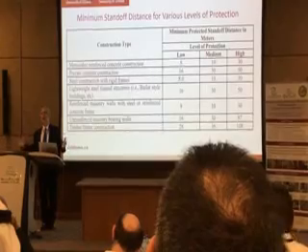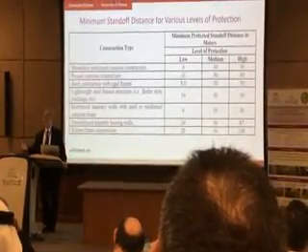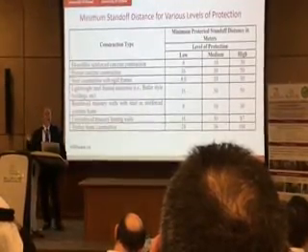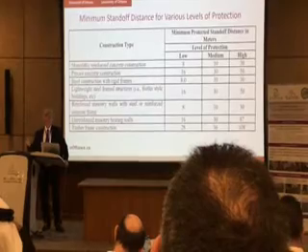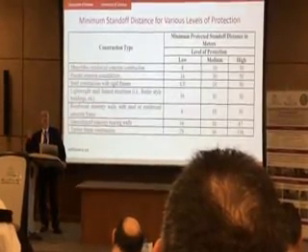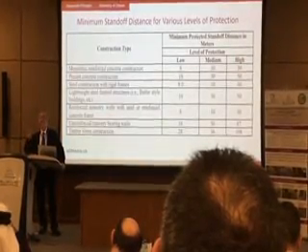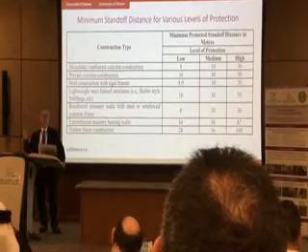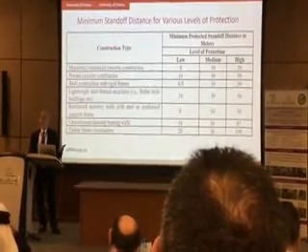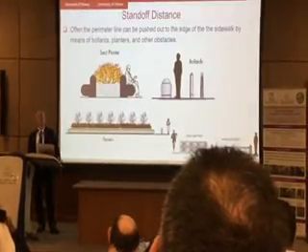If you have massive structures, as in the case of concrete and masonry, that helps. Obviously, you have to have sufficient reinforcement to increase inelastic deformability, ductility; that's another method. But in terms of mass resistance, concrete is the best material for blast resistance, as opposed to light gauge steel, which is the other extreme. So, based on the material used in construction, there are minimum recommended standoff distances, as you can see.